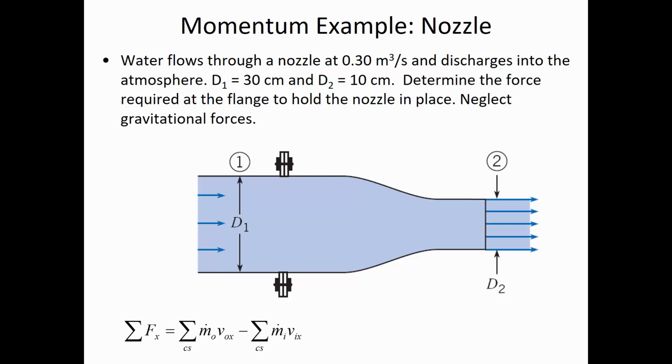And so let me reproduce this sketch here on the whiteboard. We've got the water coming out, and then here's our control surface that we put here. There is a pressure inside the pipe that is acting as though it's an external force. So we've got some pressure in the pipe, and it's acting over a certain cross-sectional area, and pressure times area is force.